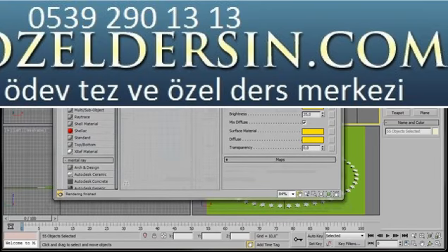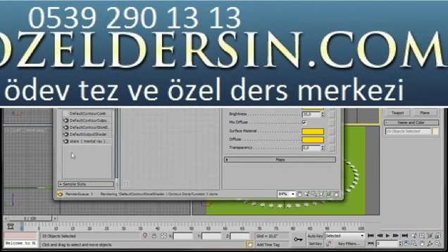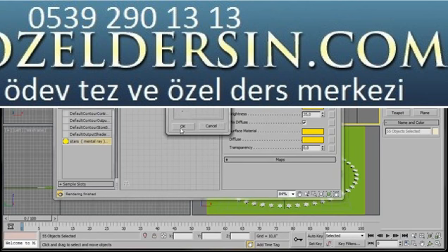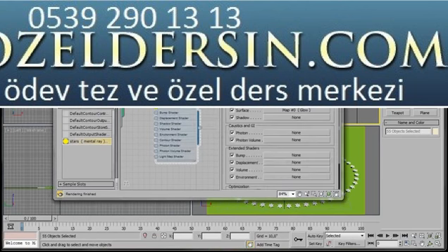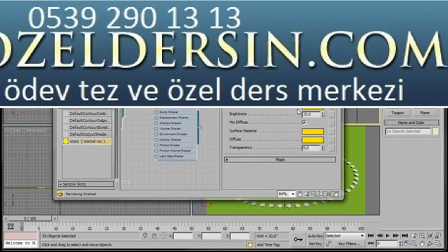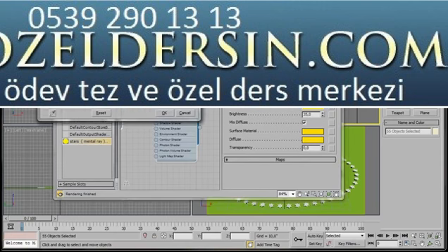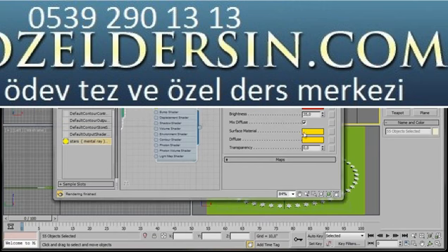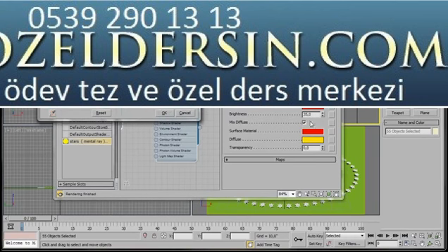We can create another material now, but this time we're just going to make a copy, so we'll scroll down to Scene Materials and we're going to drag out the material we just created, star. Select Copy from the dialog, then press OK. Okay, now we're going to double click to open the material and change the name to Sphere. All we have to do now is change the color in the glow shader, so let's click on the map, and then from the color selector we'll select a nice bright red. We'll leave the brightness at 35. The surface material will also change to a bright red, the same red, and the diffuse also the same red.